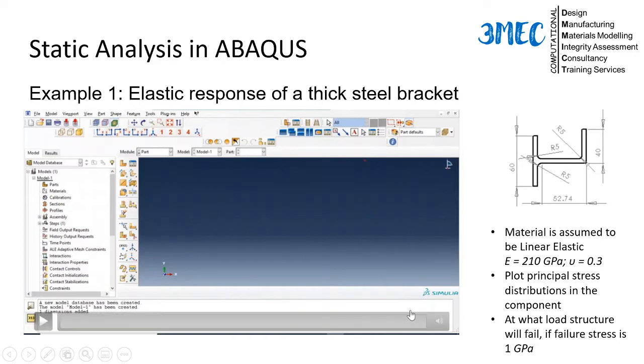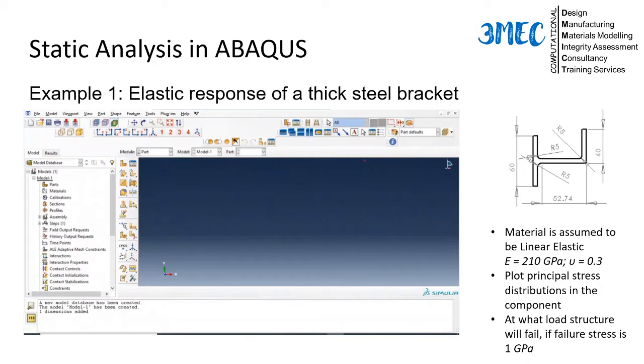So you can directly start with the 3D modeling, and as I told you, based on the symmetry you can assume something. In this case, I'm going to start with a 3D model to give you a feel of setting up a 3D model in ABAQUS. To construct this model in 3D, there are many different ways. As I give you one way, you can create this profile sketch and then extrude. But even to create this profile, there could be different techniques, because you have a lot of fillets here, as you see, R5s, and then some thicknesses and radii, etc.